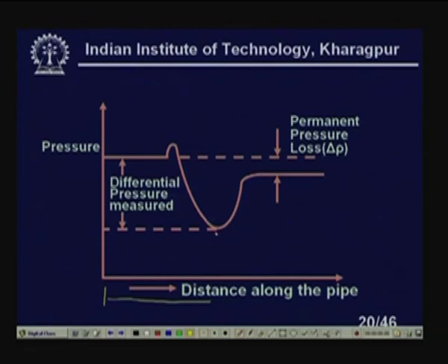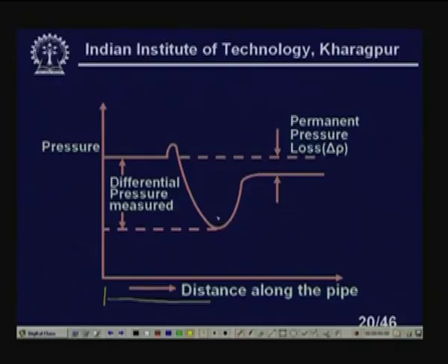The wider the pressure loss, if it is temporary, the better for measurement, because our instrument sensitivity will be higher. The pressure drop or differential pressure should be higher and higher, because our input is the flow and output is the differential pressure. So, if differential pressure by flow is higher and higher, obviously that is better for us, because static sensitivity will be increased in this case, right.